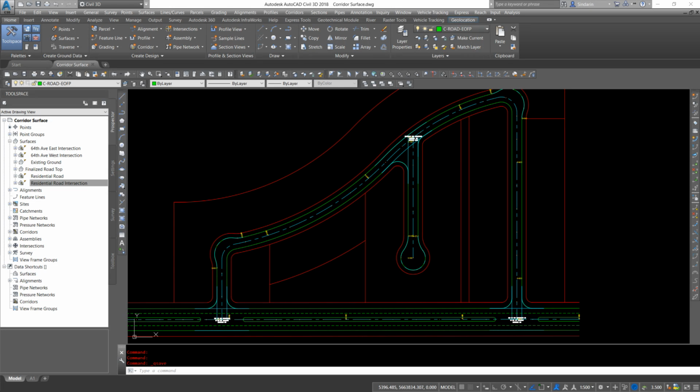In this video, we are going to try and diagnose some of the corridor-related issues that we experienced in the last video. The main one being this side of the intersection being dragged down to elevation 0. And we'll go through a couple baseline edits.